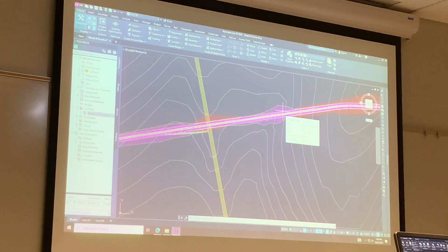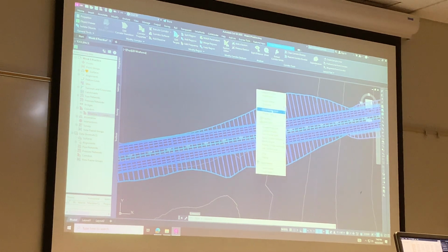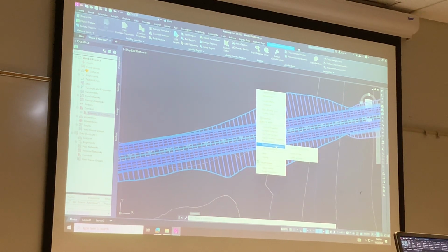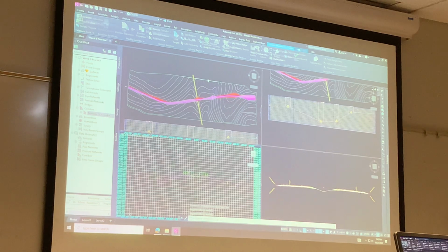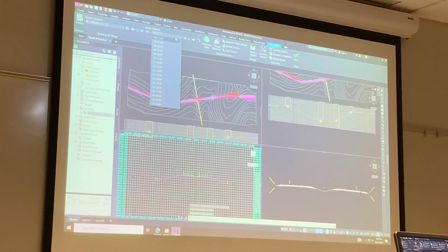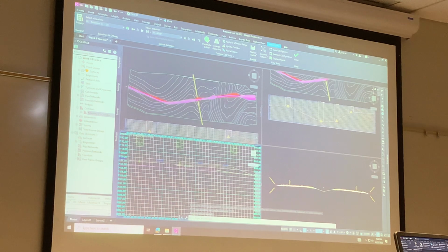And that's pretty much where we left off last week, right? I think so. Yep. And then what we did, just to view it, is we selected the corridor, right clicked, and we expanded the modify corridor sections and then chose a corridor section editor. And in that view, we were able to see at a certain station what the cross section looked like. So if I go over like 90 something.